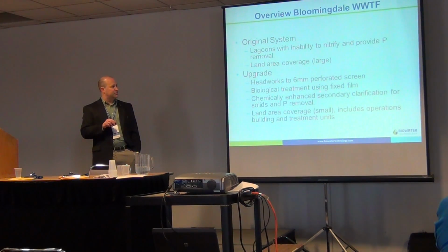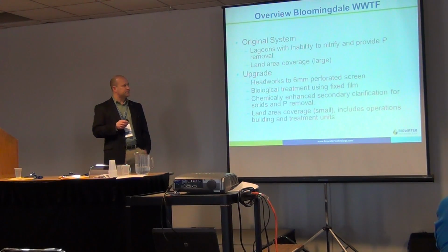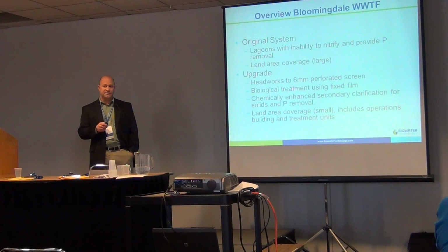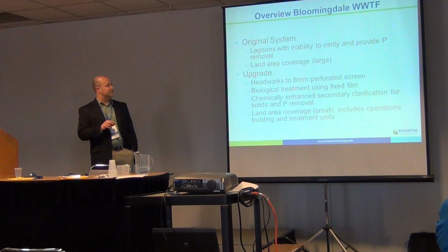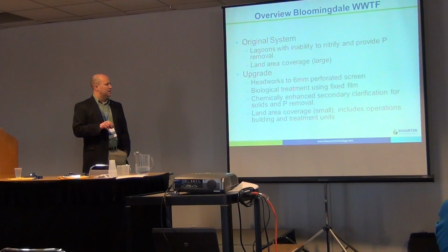We did put in biological treatment using fixed film. It's a very compact treatment system. Takes up very little space. And when we get to talking about MBBR, it's a very robust technology that doesn't require a whole lot of operator attention. So this is a very rural community. They don't have full-time operator coverage on a day-to-day basis, so they needed a system that could be checked on periodically, but not staffed on a daily basis.